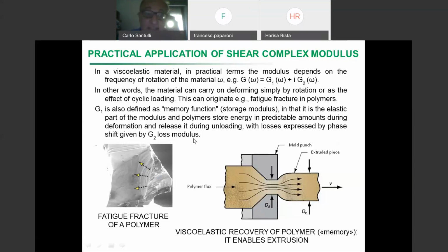In other terms, there is always a number of cycles, however low the load, that leads you to fracture, to breakage, to final fracture, or to collapse, as many like to say. And as always, fatigue fracture has this structure in rings, which is typical of this phenomenon for metals and also for polymers.